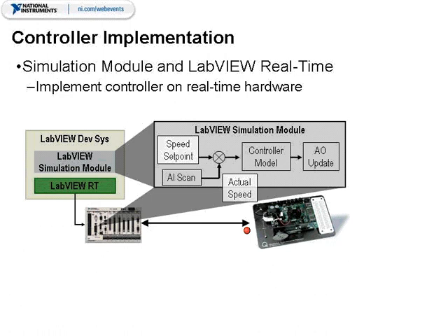Thus, the LabVIEW real-time system can become the final real-time implementation of the controller, or it can serve as a rapid control prototyping platform for an embedded control application, or later on, a hardware-in-the-loop simulation platform by replacing the controller model with the actual plant model.